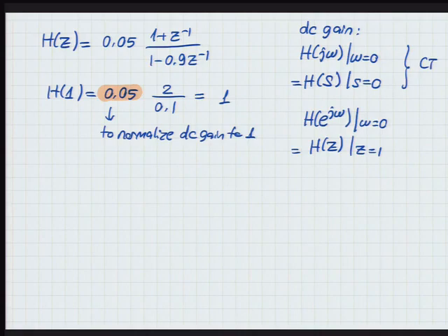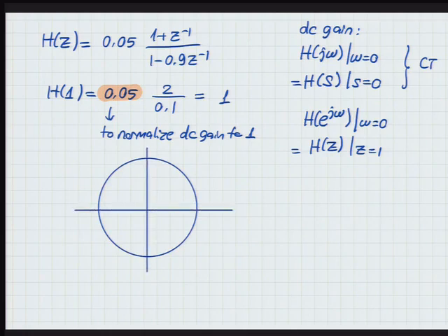All right. So now let me try to make a circle. I'm really talented with that, right? Okay, and then a straight line, another straight line. And let's mark now the poles and zeros here. Where do I have a zero? At -1. And I have a pole at 0.9, right? Okay, so then we do our walking experiment. We start at 0, we walk around the perimeter of the circle, and then we measure our distances to the pole, and let's call that vector v1 as we did before, and let's call the vector that connects us to the zero v2.